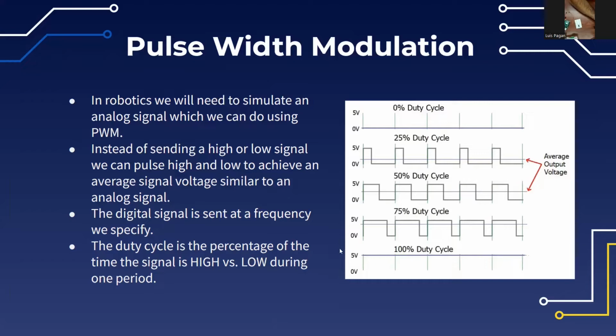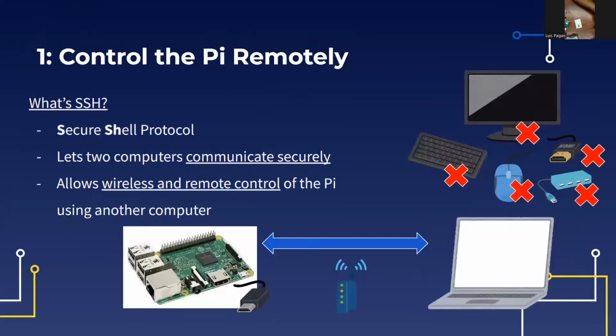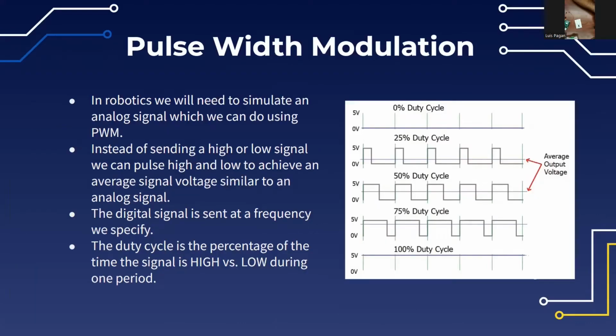So we can change the frequency and the duty cycle to get the voltage range that we want to simulate, to control the speed, or power output, of whatever pin we need. Now again, only some pins are capable of this. On Arduinos, they're the analog outs, or A something. For Raspberry Pis, there are PWM pins, and there are only 4 of them. So they're not as common as just digital pins.